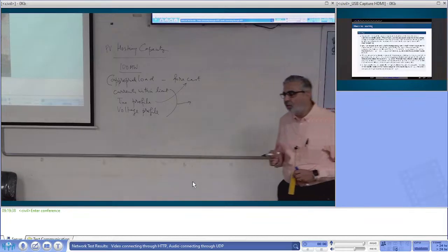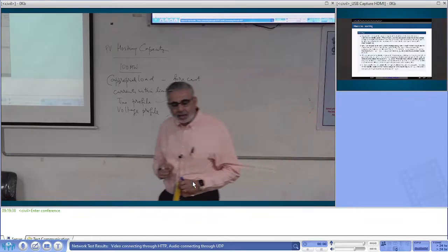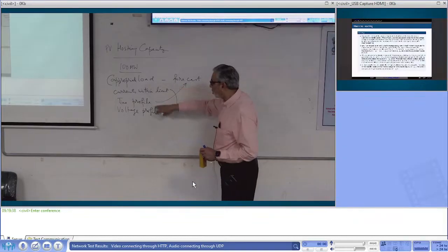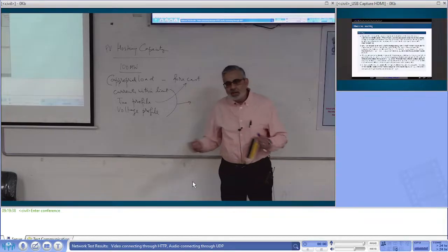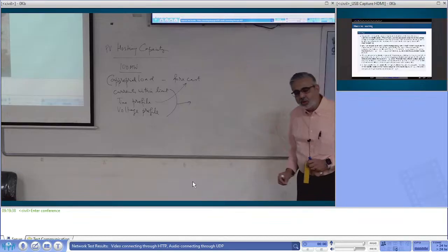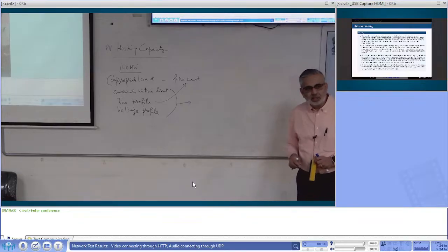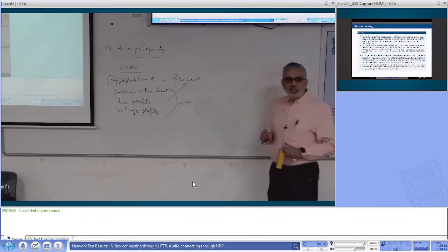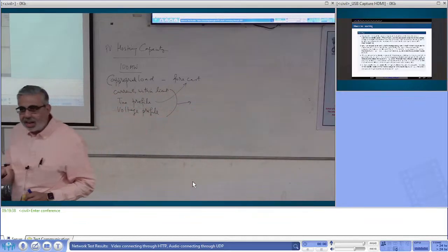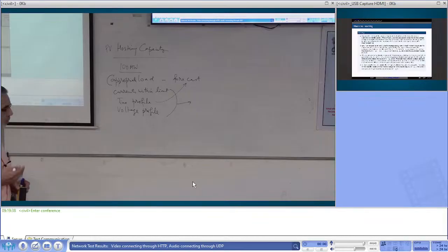Finding current limit and voltage profile. Are they related the same way, or are they separate? We have to hire one person to do this and another to do that, because load and sun may not be related. So we tell someone to give us the sun, and someone else to give us the load. Then we have to integrate it with our thing. So whom do we approach to get this? If we can't get this reliably, our hosting capacity estimate will never be good. So what is the type of analysis we need to